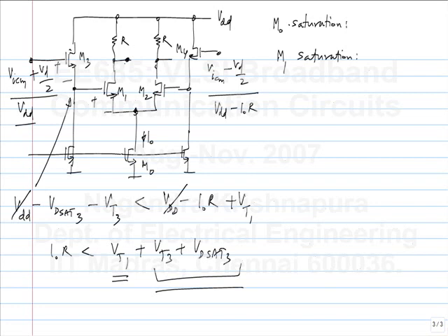It's trivial to see that the supply current is a constant because this is a current source. The current through the supply and ground is always constant. That got rid of one of the problems of CMOS logic, where the switching current was flowing through the supply lines and causing problems. Also it is a differential circuit, both the inputs and outputs are differential, so it gets rid of the crosstalk problem to a great extent. And the reference problem, that is, the output is measured as the difference between these two, not between this and some ill-defined ground. So that problem also has been got rid of.